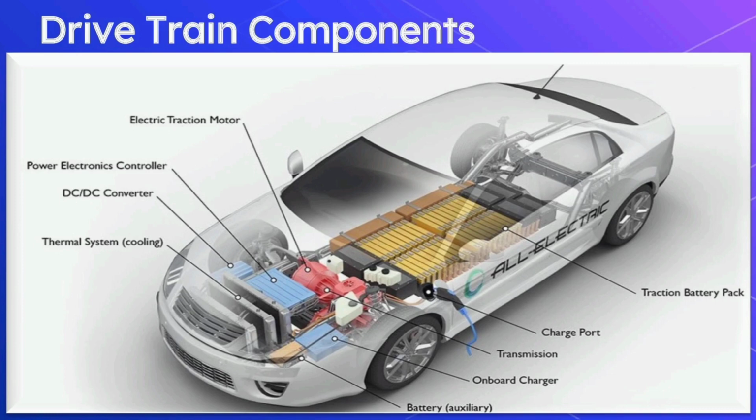This slide shows the introduction of hybrid drivetrains. The term hybrid vehicle refers to a vehicle with at least two sources of power. Hybrid electric vehicle indicates that one source of power is an electric motor. There are many types of hybrid electric vehicles, such as gasoline ICE and battery, diesel ICE and battery, battery and FC, battery and capacitor, battery and flywheel, and battery and battery hybrids.